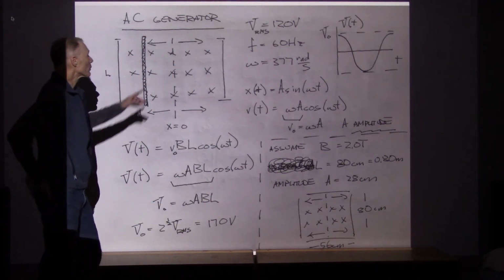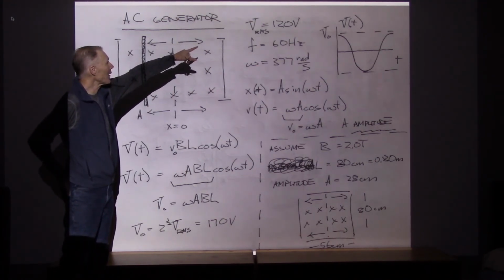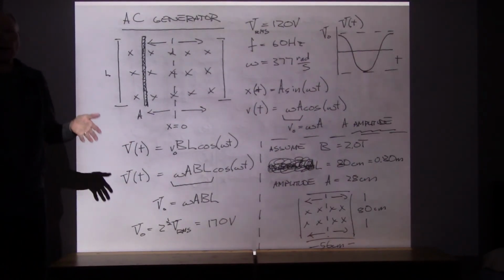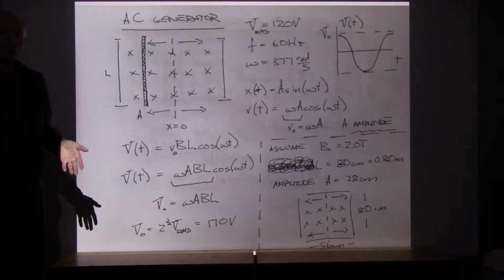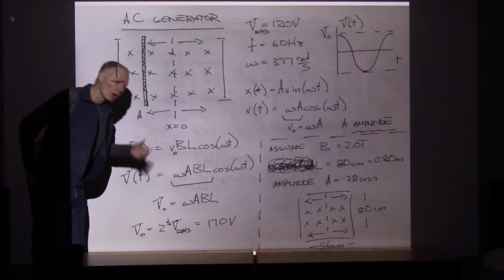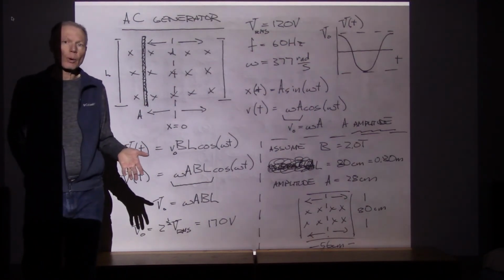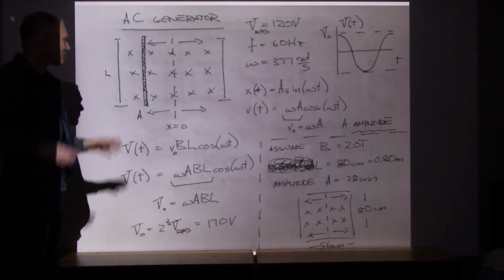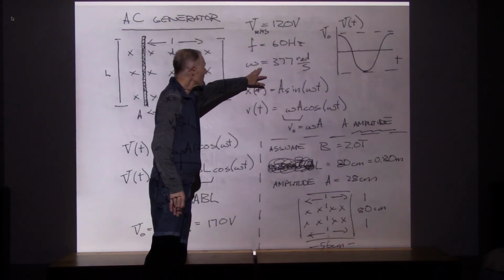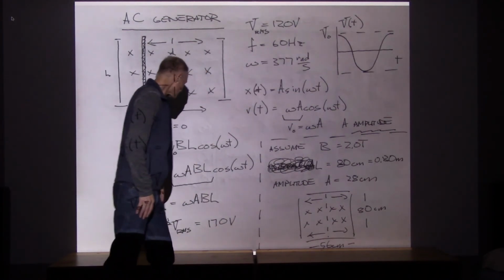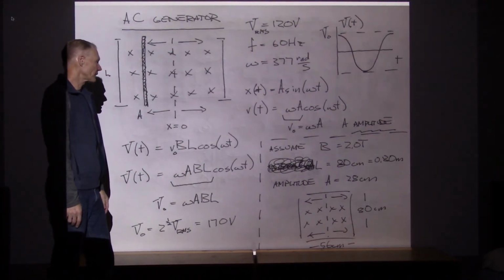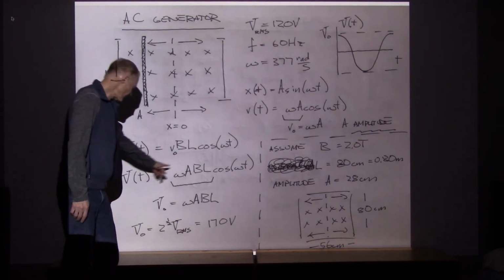Now, if you remember, the voltages that we have in our outlets, they're listed as 120, but that's a type of averaging. It's an RMS averaging that we use. The peak voltage of our outlets is actually larger by a factor of the square root of 2. So that means I really want these specifications. I want an omega of 377 radians per second, and I want a peak voltage of 170 volts. And then this is my formula.